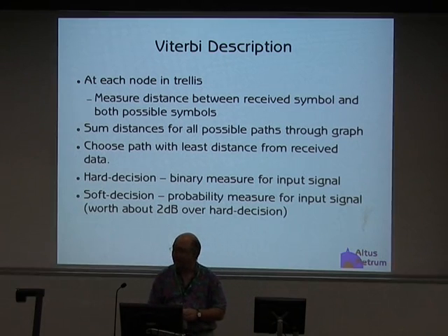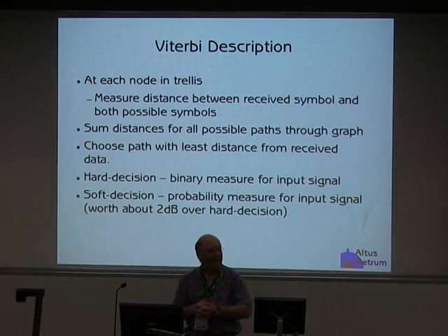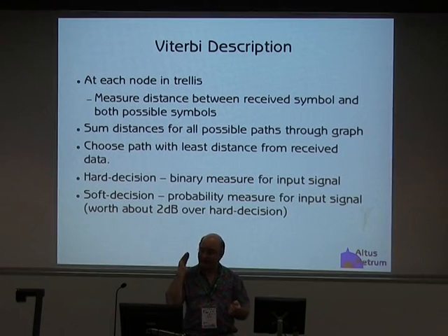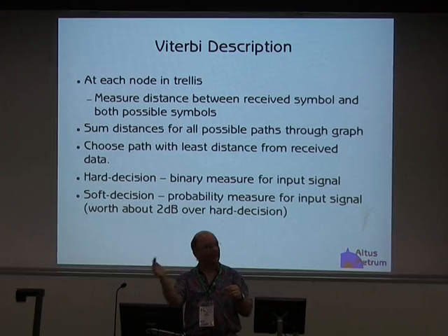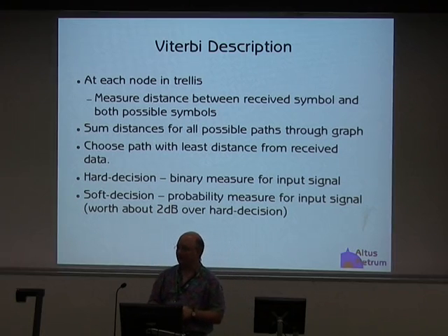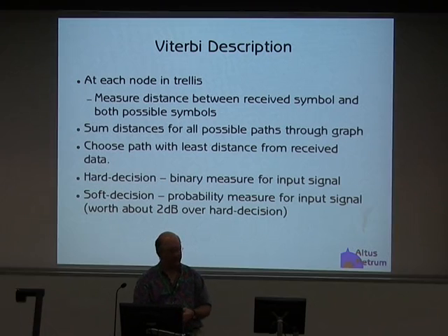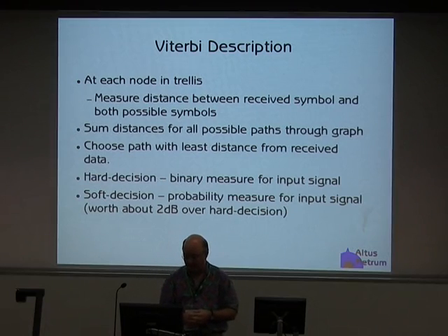And then you have soft decision, where the receiver says, I'm not really sure what that was. It was more like a 1 than a 0, so I'm going to say it's 0.7. Soft decision is awesome for frequency shift keying, because what does your FM demodulator give you? Your FM demodulator actually gives you a frequency between the two bounds of your modulation, right? It says, that was 0.7 volts instead of 1 volt or 0 volts. And so your frequency shift receiver automatically gives you these soft decision values, as long as you can bother to get the hardware to hand them to you, which the hardware that we're currently using is very reluctant about.